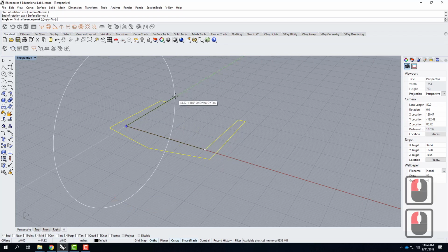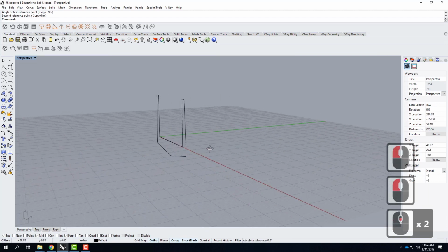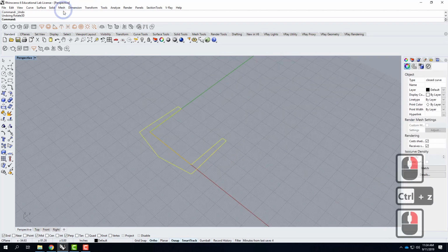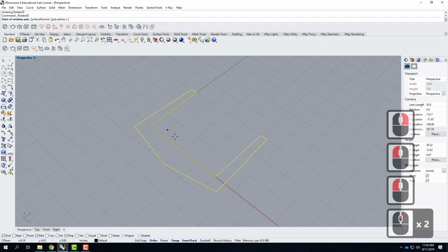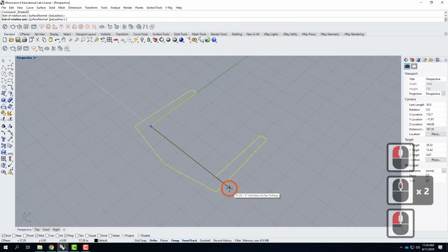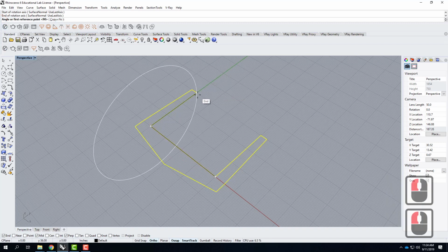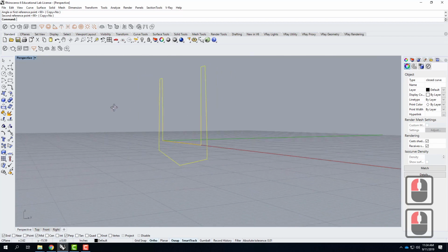And then my reference point would be going right up this side, and I'll have it jump into its 3D position like that. So one more time, it's the rotate 3D. I'll go to transform, rotate 3D. My axis of rotation is going to be right here. My reference is going to be going up this side, and I'll fold it up so that it's standing up like that.